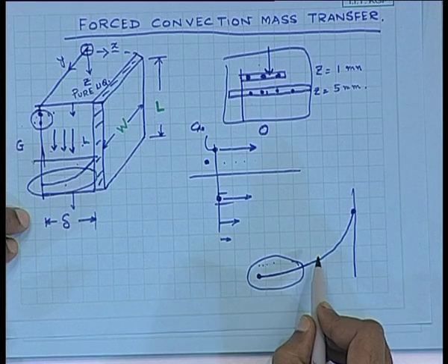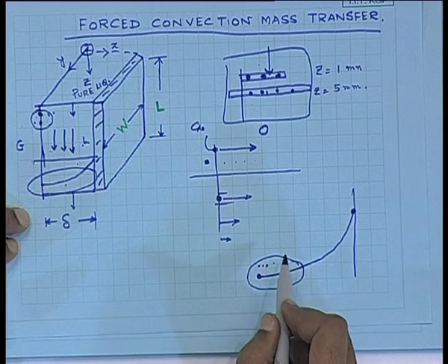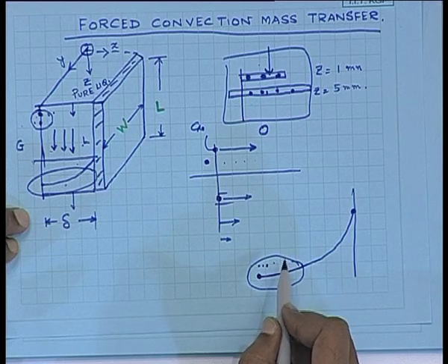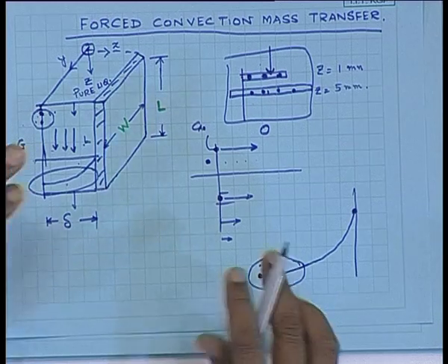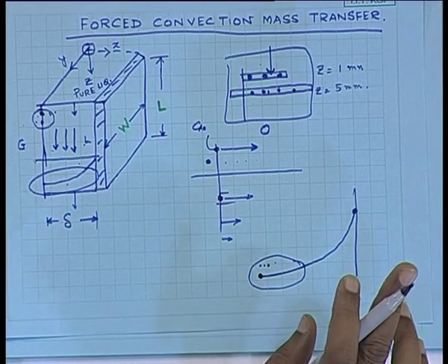So if the penetration depth is small, then the absorbed gas molecules, with which velocity will they travel? Is that clear? The profile of the velocity is like this, a parabola. So if the penetration depth is rather small, then all absorbed gas molecules can be approximated to travel with a velocity equal to this one, which is V max. All right. Is that part clear? This assumption makes us use a constant value of velocity.